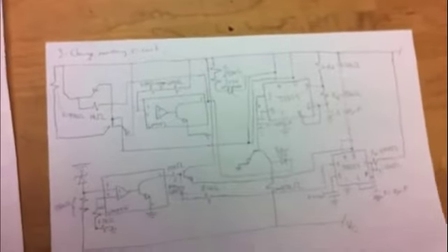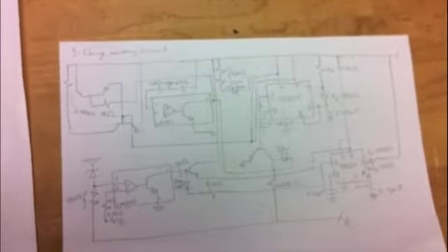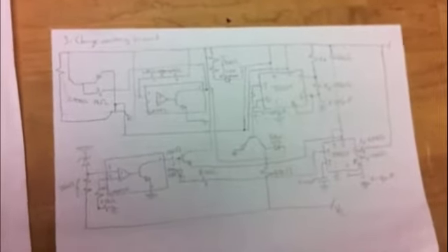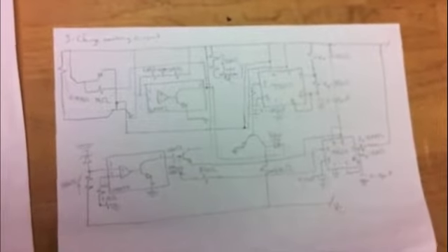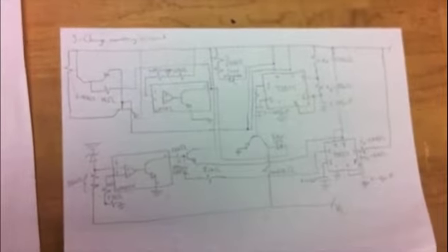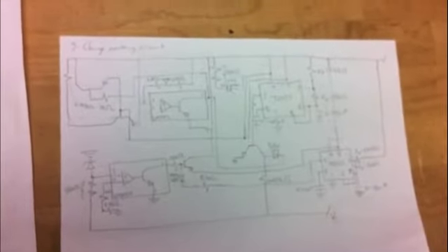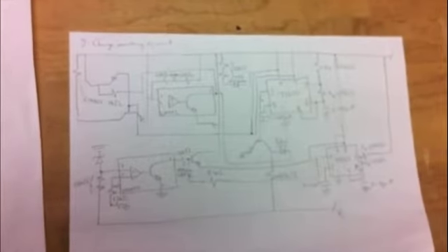This is our charge monitoring circuit. The purpose of the charge monitoring circuit is to light one of the 2 LEDs depending on the capacitor voltage. If the capacitor is more than 50% charged or greater than 4 volts, the green LED will illuminate. Conversely, if the capacitor is less than 50% charged or less than 4 volts, the yellow LED will illuminate. When lit, the LED will flash for about 0.1 seconds every 2 seconds.